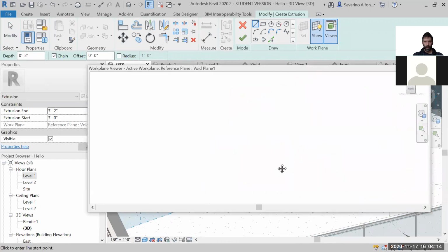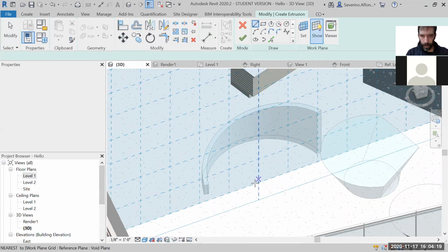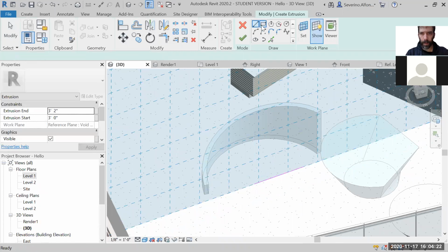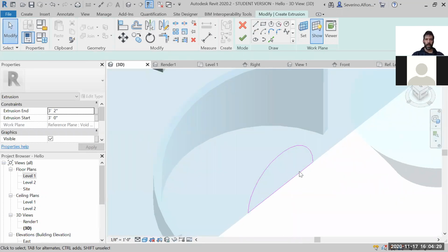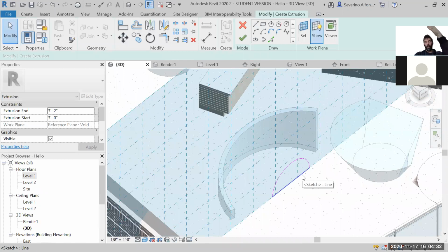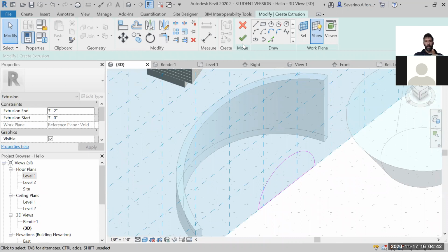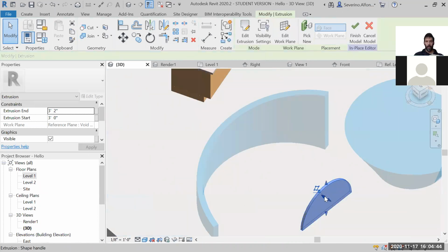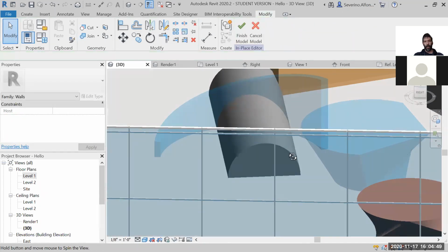We used to work this thing, I don't know what's happening. Anyway, I can create a curve here, a closed polyline with a particular curve. And what I'm doing is an extrusion in a different direction. Since I created a reference plane that is vertical, I say I want to do an extrusion, and I selected this plane to create the curves that I want, or the closed polyline. Then I can say, okay, it's going to extrude in one direction. I could take it all the way, and it would be going through that element.